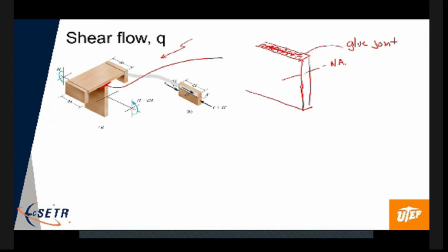This shear force here, we'll call it delta V for now, right? Because this distance here, we'll do it over a finite section. So this distance here is the delta X, okay? So we know the shear stress on here. We could calculate that. We can get that tau. That's going to be the VQ on IT, right? Okay, so we calculate that.